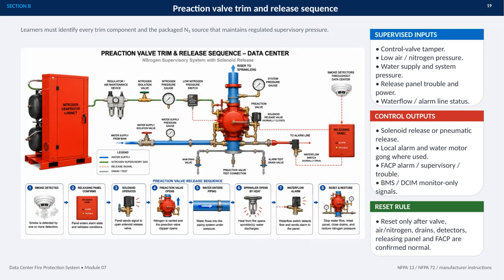The reset rule is critical. Reset only after the valve, air or nitrogen, drains, detectors, releasing panel, and FACP are all confirmed normal. Always follow NFPA 13, NFPA 72, and the manufacturer's instructions.